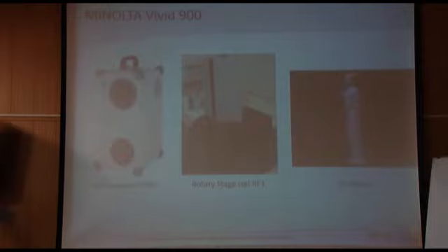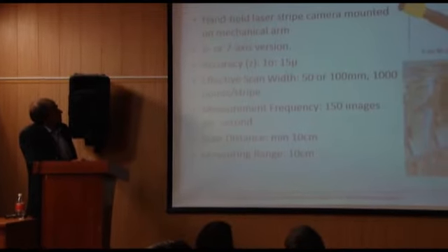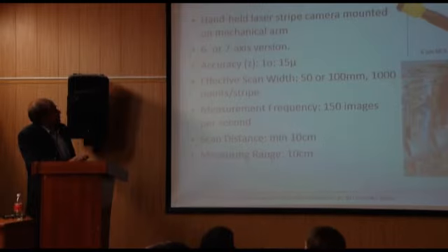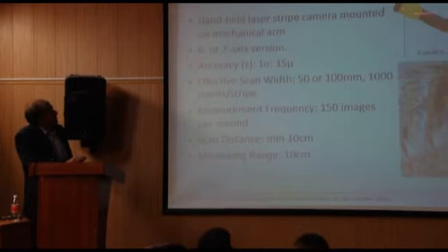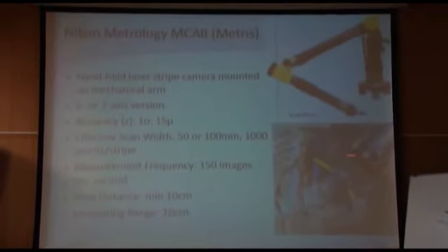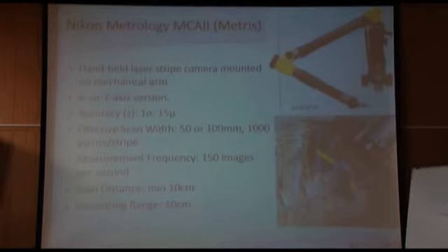So here everything is done automatically. You just need the turntable and the scanner. Another way to do that is, for instance, by Nikon, where you have an arm, and this arm is encoding the angle that the arm has, and with this probe you just go onto the object and measure the distance. So you have to do it manually, but you can always control on the monitor if you have reached all points of the surface.